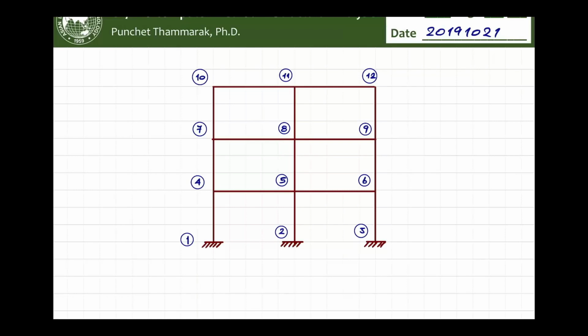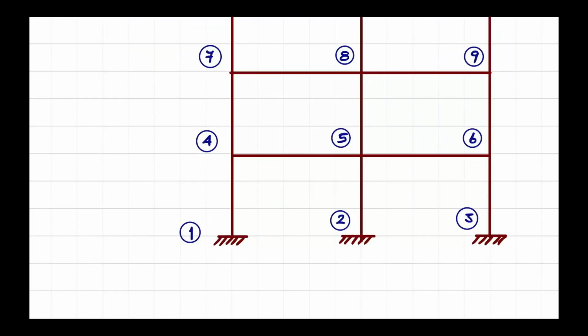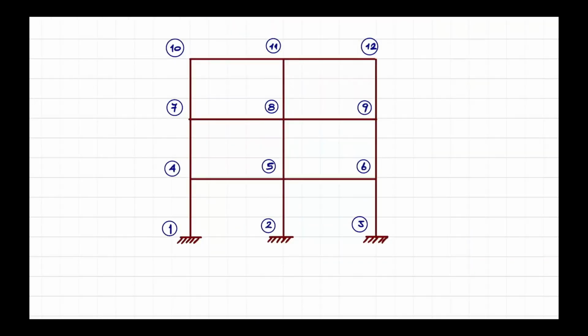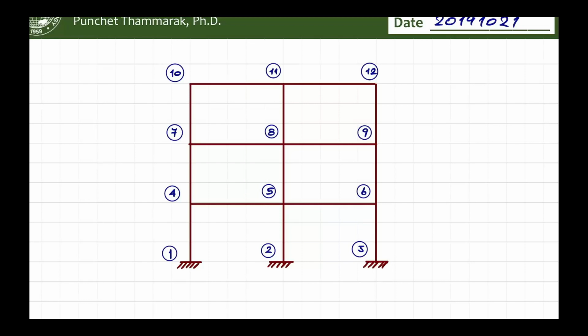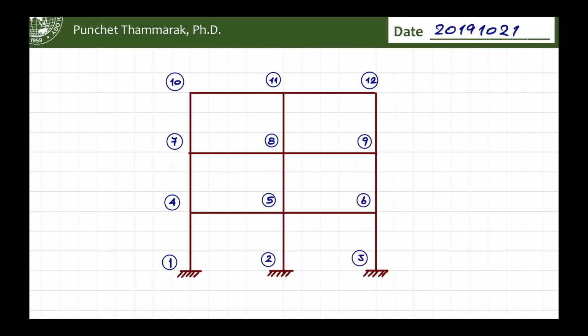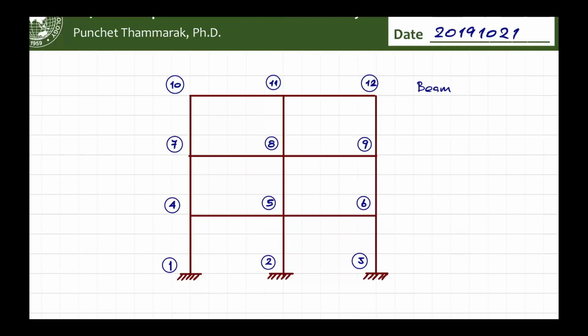We will have the element numbers and also the description for each element. First of all, let me give you some idea. For a building like this, a few story building, generally the size of the beam cross section should be somewhere around 20 by 40. The span here is 5 meters, so make it 20 by 50.